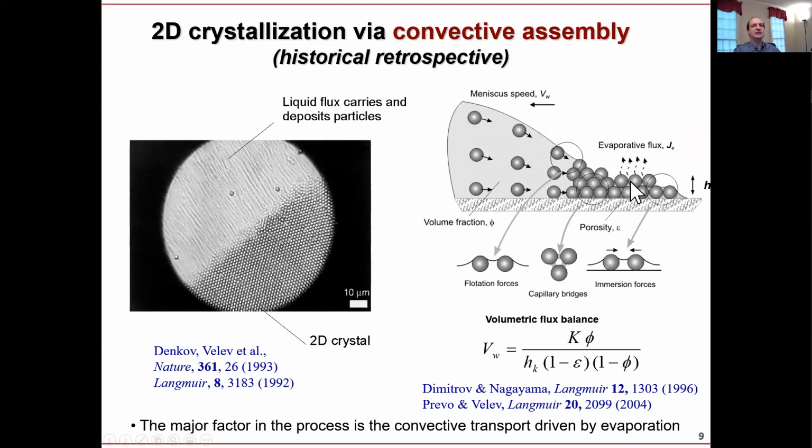For a multilayer, essentially, you are going to have this evaporation taking place, and the particles would remain, the liquid is going to leave. So this is how you deposit a layer. This is how you make coatings in general, if you think about it. But in this case, the difference is that the coating is made in a way that the liquid that gets drawn in is going to be bringing the particles. So you essentially have a moving front. You do not dry it like that, you draw it at a moving front. And because you do that, you can organize the particles very well, and you can have the colloidal crystals, the beautiful color and everything.